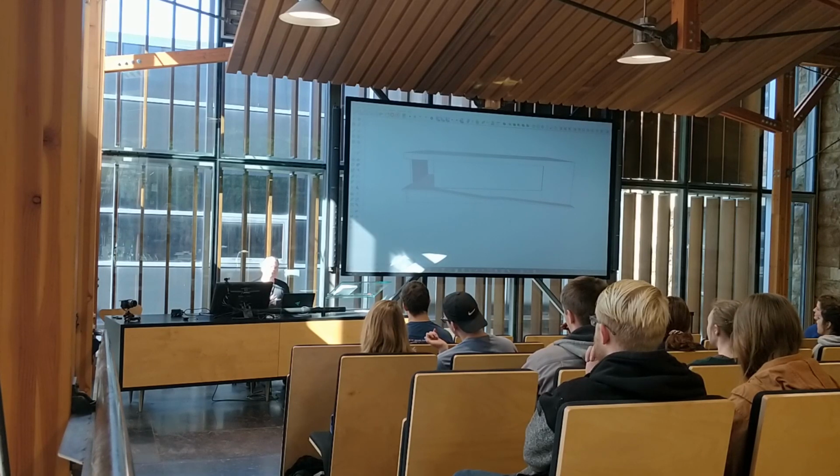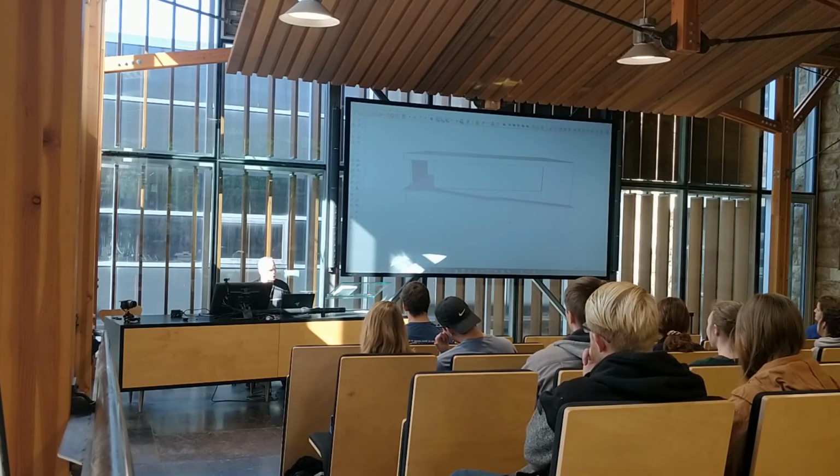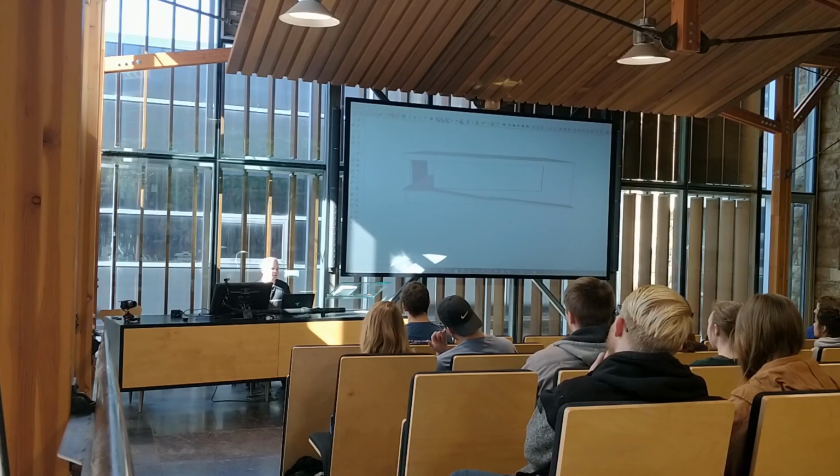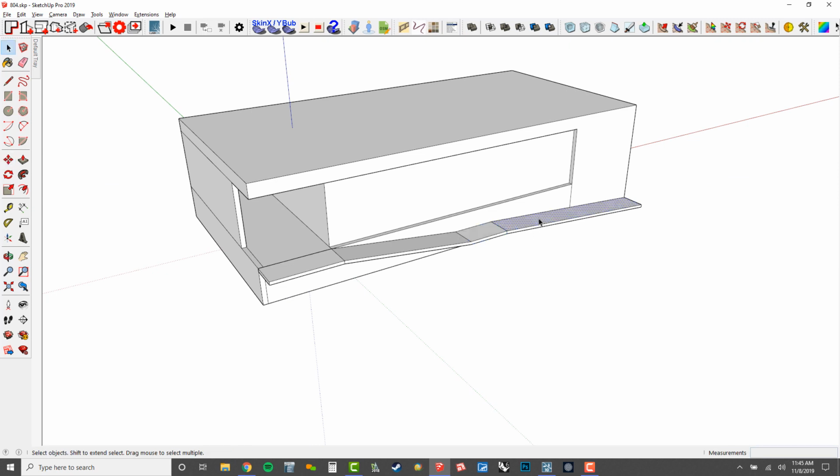So that's what I think is so powerful about SketchUp, is that I can just get in there and get going. And I don't need a bunch of templates and wall types and sheets and all these things that a lot of other programs require just to get going. So I think we're in good shape there. We've got our ramp. Again, I would just triple click that, make it into a group.